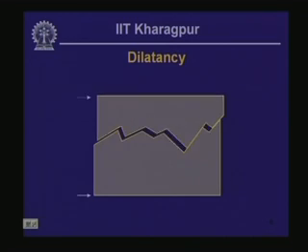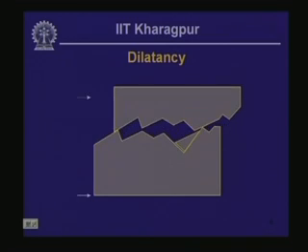So what happens here is that the top piece tries to climb up as it is sheared to the right of this screen, and this involves a change of volume. You should have also noticed that the void space in between the top piece and the bottom piece increases during this process, and this type of behavior is called dilatancy.